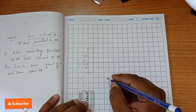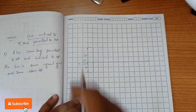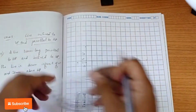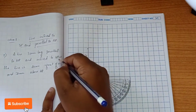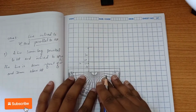Whatever inclination we have given to VP, we can show it in the VP plane. Sorry, in the HP plane. Inclination to VP, we have to show it in the HP plane. Let's say the inclination is 45 degrees, so we will give the angle of 45 degrees.